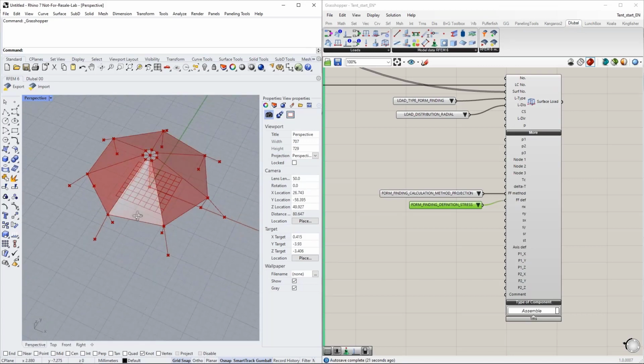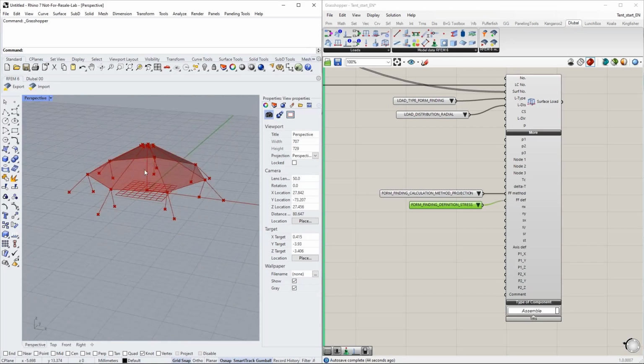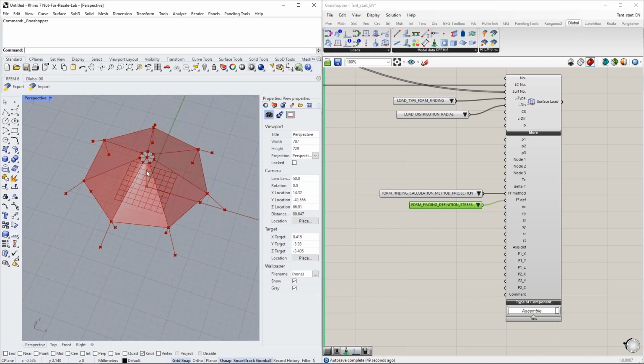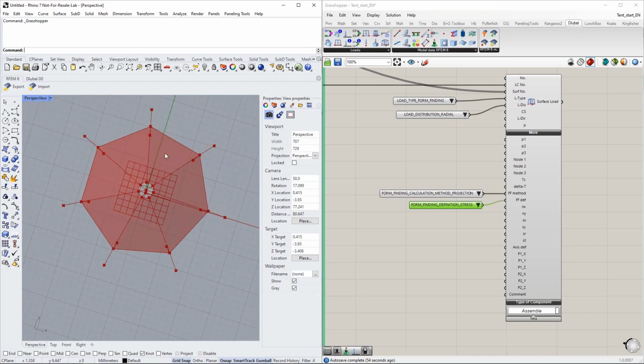And in the past, we had to modify the internal local axis system of my surfaces. They had to be directed into a specific direction, one for radial, one for tangential. And then I was able to assign it. With this new load, it's not required any longer. I can simply say I have a rotation axis, let's say upwards, basically similar to my center column. And then the load knows, okay, tangential means this one, radial means this one.